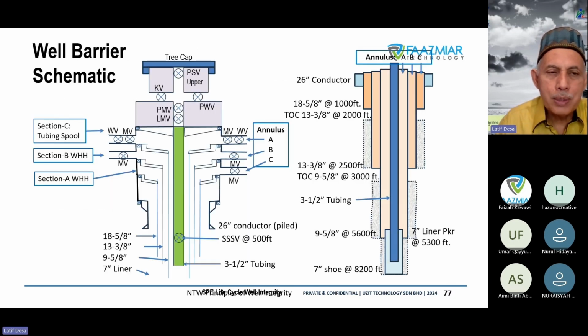Okay, so normally our system here might be able to help us with the drawing. For example, sometimes we have a consistent drawing, so everybody will understand the style, which one is the triple SV, which one is the primary gate valve, wing valve, and then the lower master valve. All these terms tell you that this is the component exposed to the wellbore and its potential failure is quite high. So we have to check with integrity.